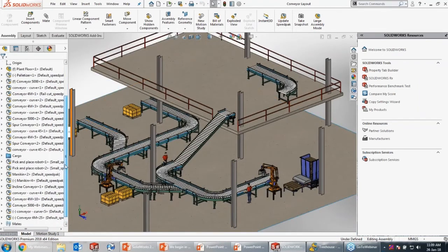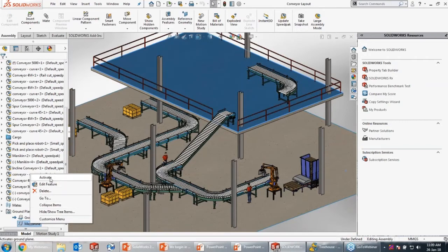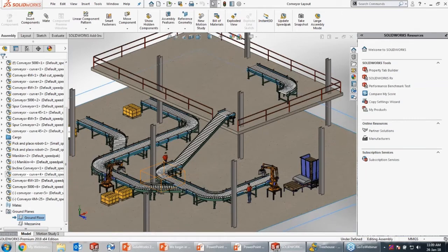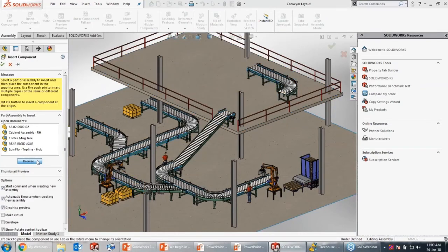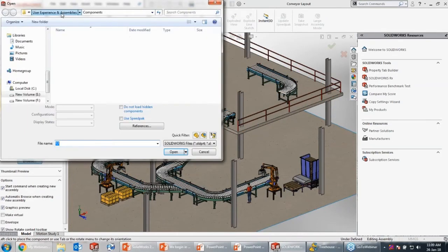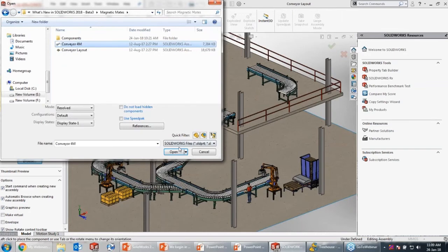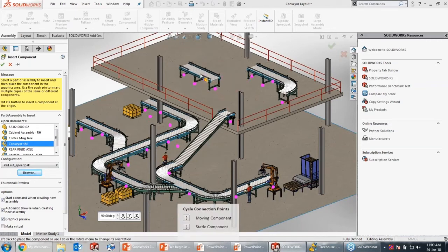Every time I'm adding a new part, just by clicking the Tab key, the basic orientation of the part changes. Once this is completed, the locking of the magnetic mates has been made simpler, just a click away, and there is no necessity to browse to the mates folder and then lock the magnetic mate.